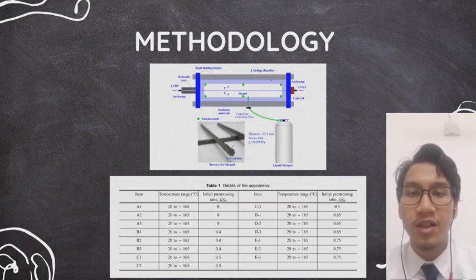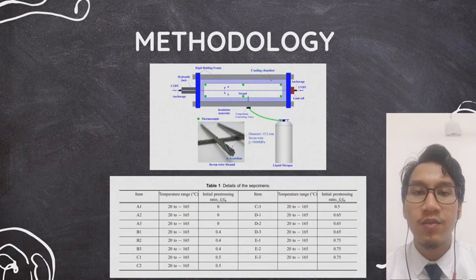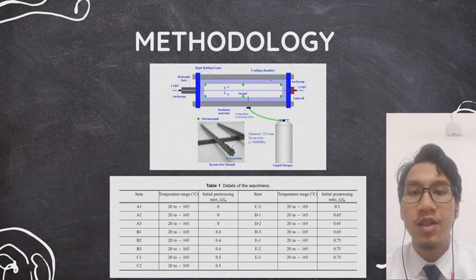After the pre-stressing on the strand, liquid nitrogen was injected into the cooling chamber. 6 thermocouples were variously distributed on the surface of the steel strand to monitor its temperature. After achieving the target temperature of -165 degrees Celsius, the injection of the liquid nitrogen was controlled to maintain this temperature level. Then, the steel strand was pre-stressed to the target pre-stressing level, and this pre-stressing level was maintained during the thermal expansion behavior test.